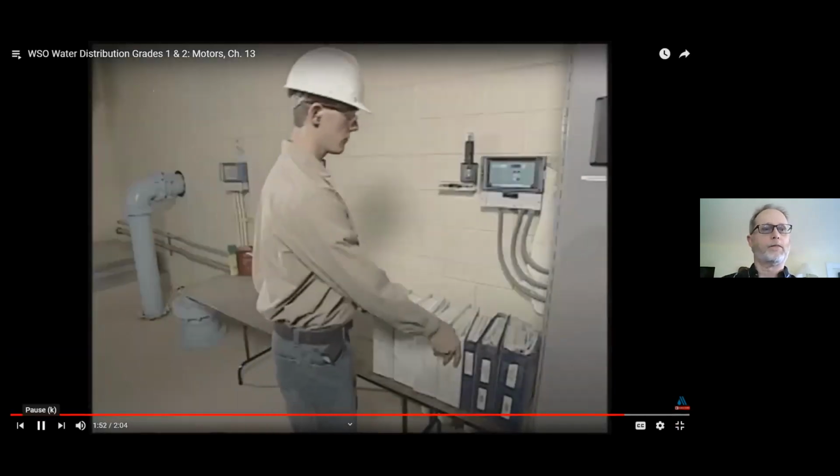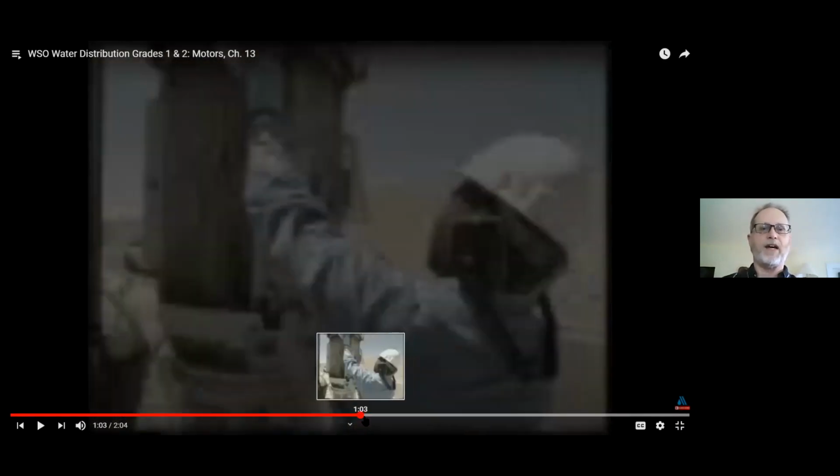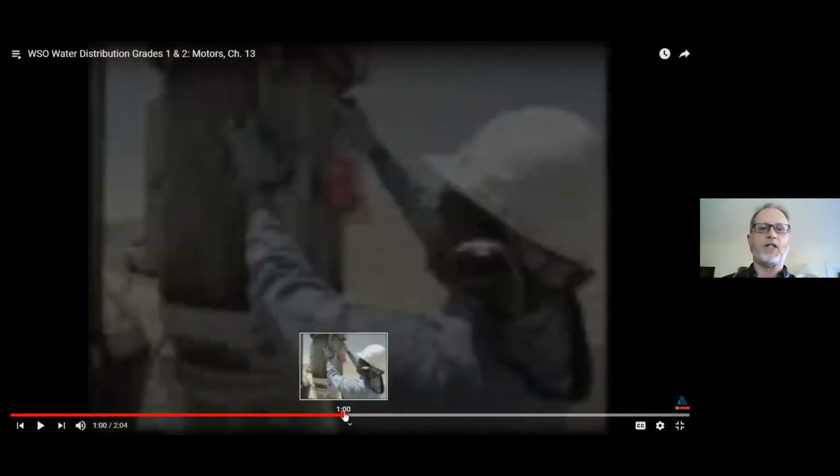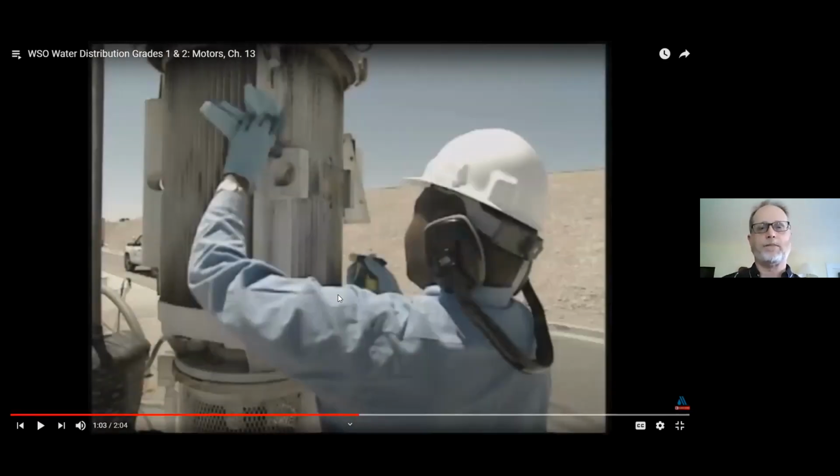So one of the key things in here to look at is with the three-phase. You mentioned that obviously maintenance is important, and dust is a big issue with motors, and heat, right? We've got to keep the motor within the manufacturer's recommended operating range for both temperature and overall air quality. So there may be filters in the room where the motor is, certainly ventilation to keep temperatures down.